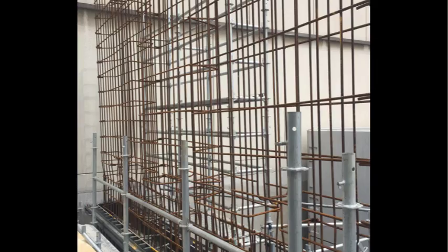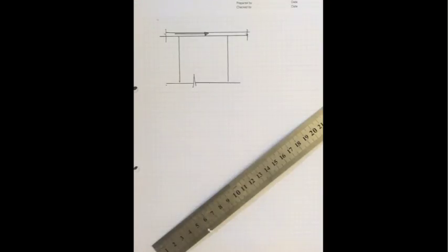Where we have some strength contribution from the concrete itself. Here we have a picture of a shear wall showing some of the steel that is going on. So we have horizontal steel and vertical steel helping toward the shear. Next we have section 11.6, design of walls for in-plane shear forces.